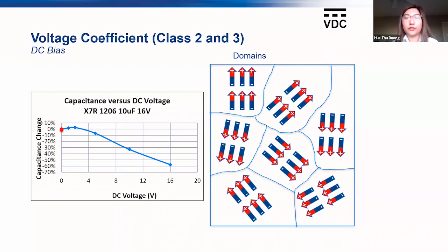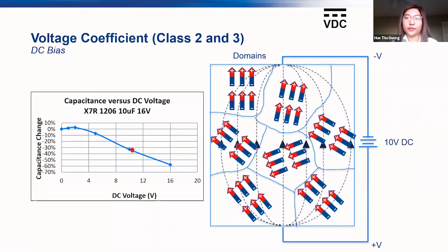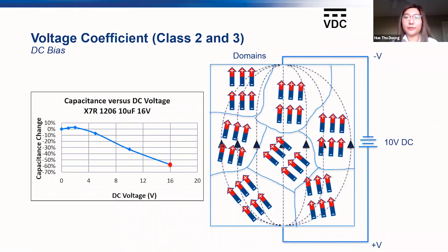So now, when we apply an electric field on the material, the titanium ion will shift within the crystal structure and rotate the dipole to align with the electric field. The ability of barium titanate to create dipoles, and the ability of these dipoles to rotate with the electric field, is what gives the material its high permittivity. We call this material ferroelectric.